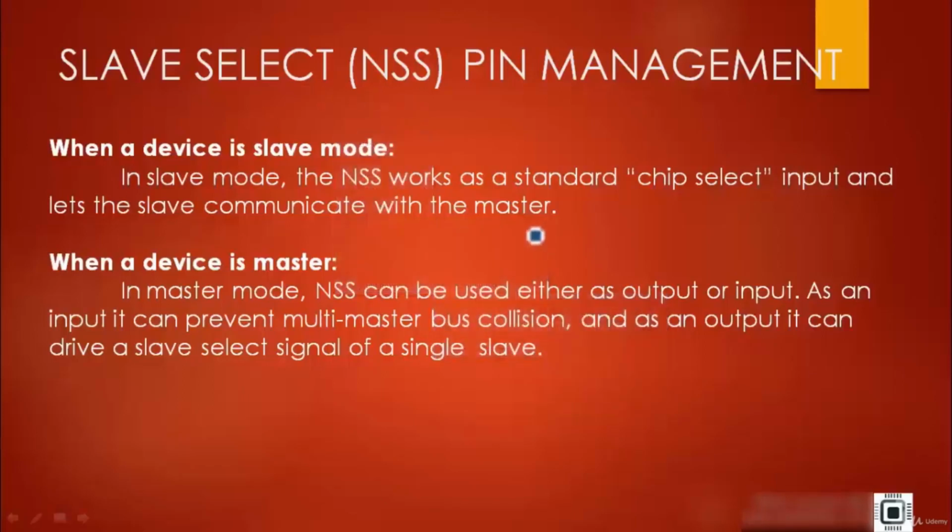So, in this lecture, let's understand the slave select pin management, that is NSS pin management. This we have to understand in two scenarios. The first scenario is when the device is in slave mode. When the device is in slave mode, the NSS works as a standard chip select input and lets the slave communicate with the master. This we have discussed. So, when in slave mode, the NSS pin will just work like a standard chip select input pin.